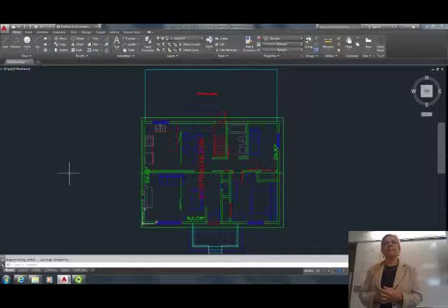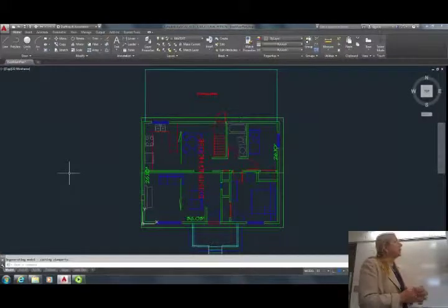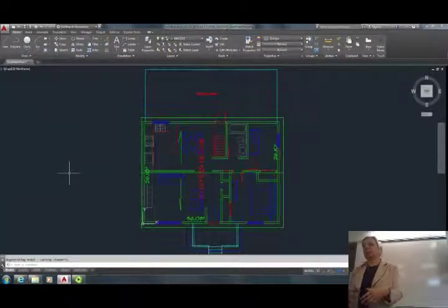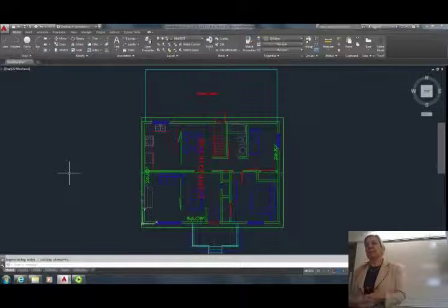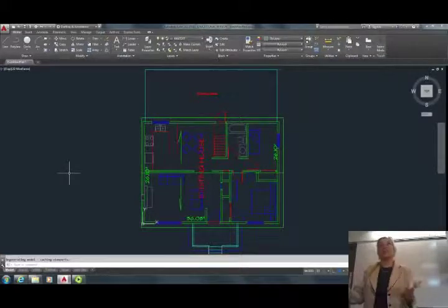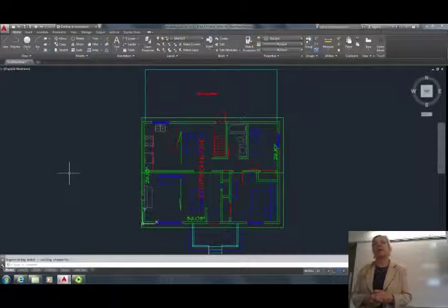So what happened in the office is you would work with standard scale, which would be 1/4 inch for plan. And what would happen is, if the boss came in and said, I got a meeting with the bank or lawyers, give me 8.5 by 11 sheets, we would most likely not even have layout tabs set up for small sheets. We would basically send the sheet scaled to fit, because the bankers and lawyers really would never even look at the scale. So if it was documentation to just show what drawings we have and just have an idea about the building size and shape up for discussion, you would just send them in the office to printer and basically print them to fit 8.5 by 11 sheet.